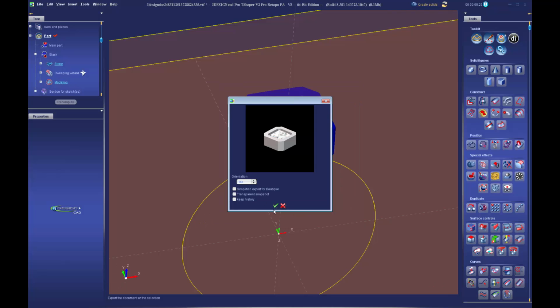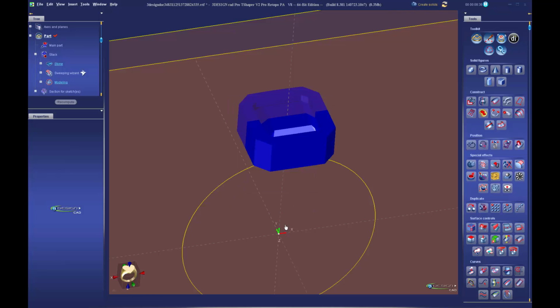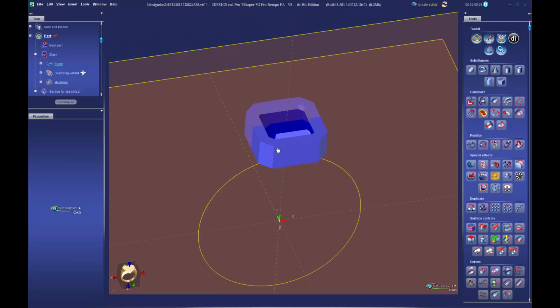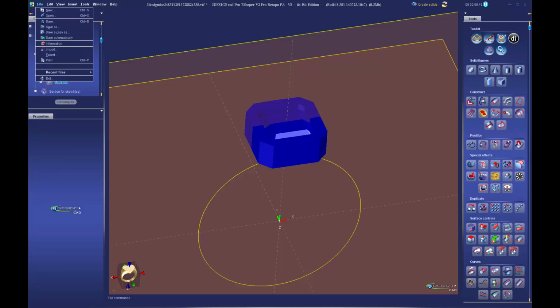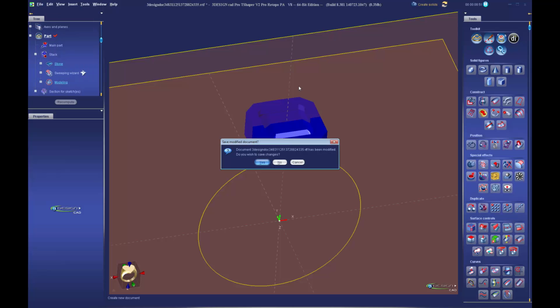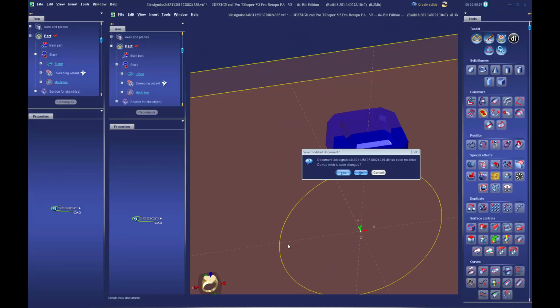And save. Okay. Go ahead and take your snapshot and make sure you check Keep History so that we can change this parametrically later. Validate that, and now we have our symbol in our library. To test that, we can't import the same symbol into the file that we created it in. It would be a copy of itself, opened in itself. Computers don't like that. So we'll go to File, New. You can save this file if you need to use it again. I'm going to hit No.